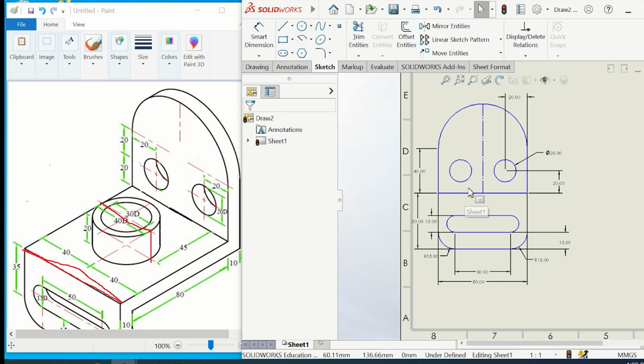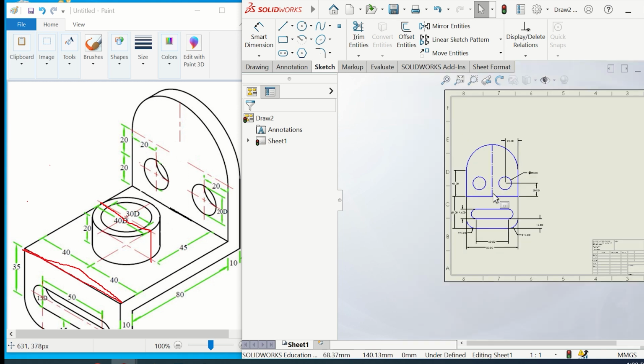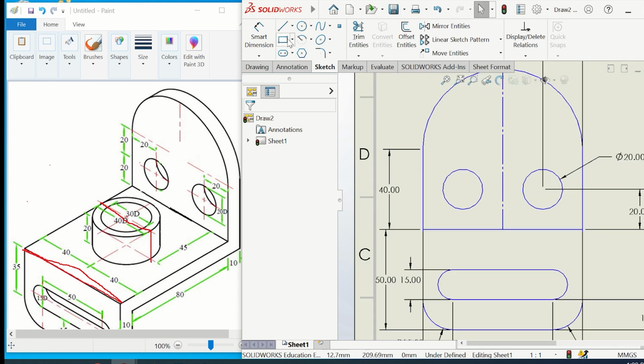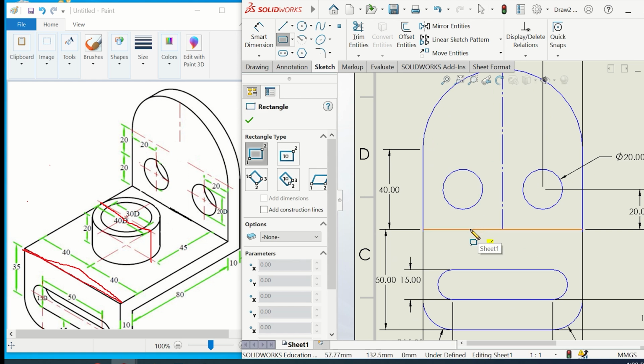As I was saying, we need to draw here a rectangle that's 40 units by 20 units of height. So I'm going to come here, rectangle. It's a corner rectangle, so the first corner point should be stuck on this line. So I'm going to click on this line, and I'm not going to click elsewhere. Let me just directly enter the dimensions, which are 20 units in height, tab, and then the width would be 40 units.